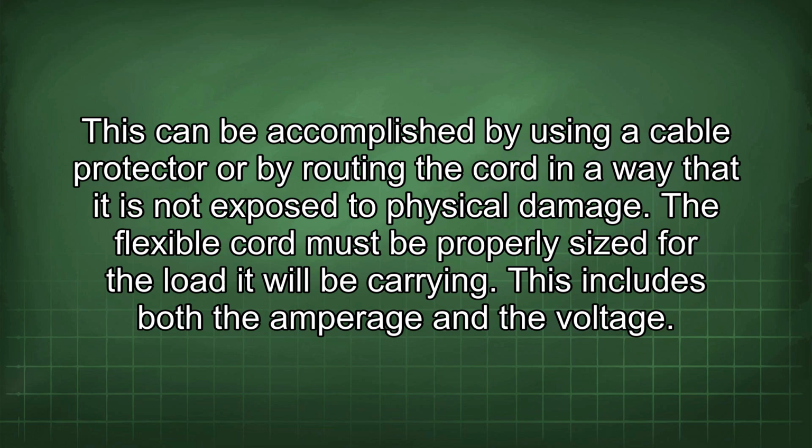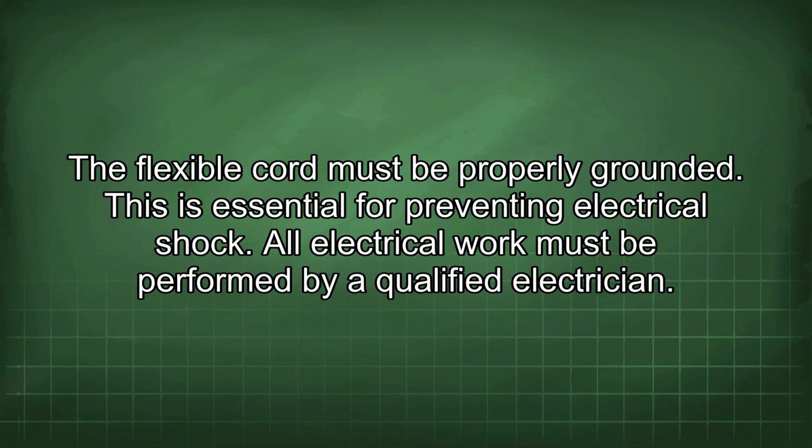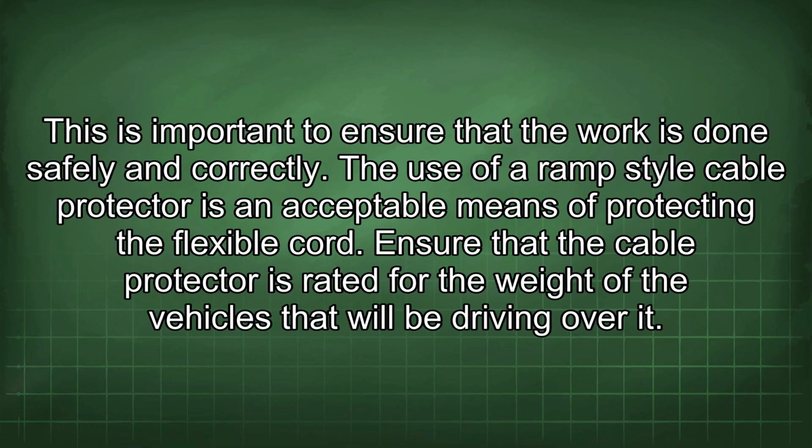The flexible cord must be properly sized for the load it will be carrying. This includes both the amperage and the voltage. The flexible cord must be properly grounded. This is essential for preventing electrical shock. All electrical work must be performed by a qualified electrician. This is important to ensure that the work is done safely and correctly.